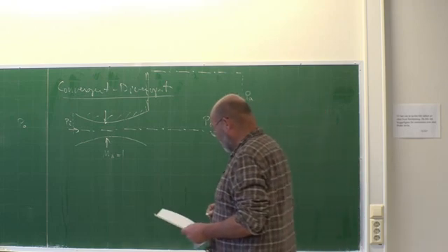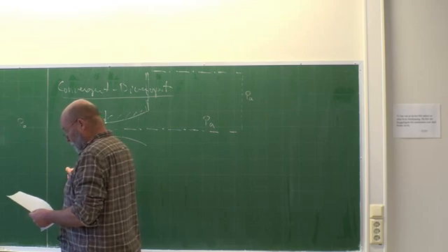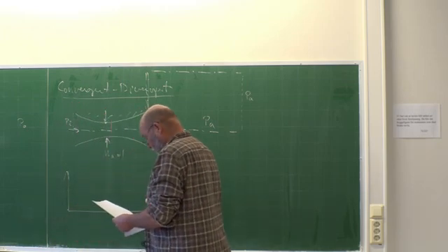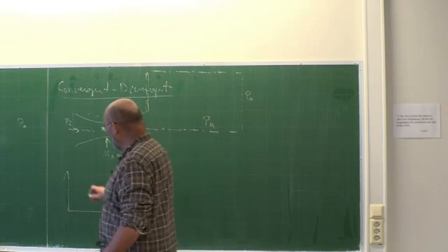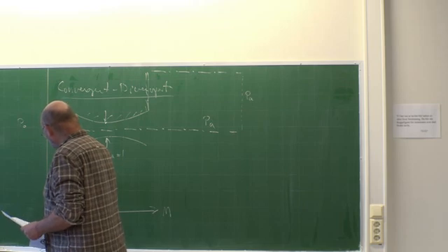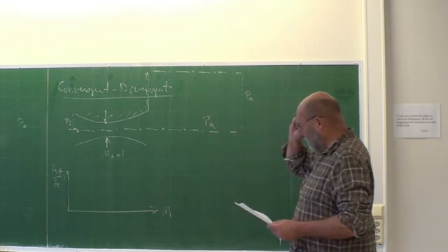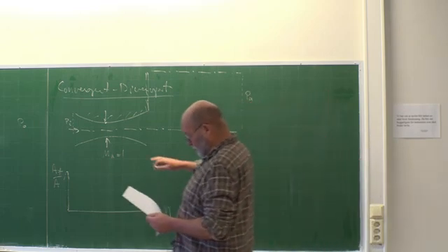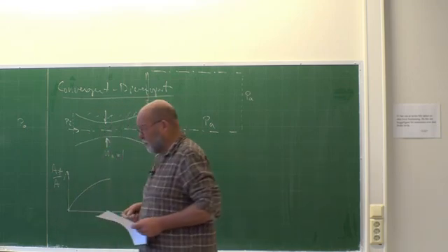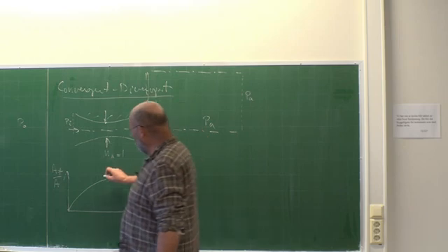So well, we can make a little sketch here. If you look at the following, we have a Mach number, and then here we will have the critical area by the actual area. What's then going to happen when you start somewhere here? Well, you will get something like this. And then it's a question, will you reach 1 or not?